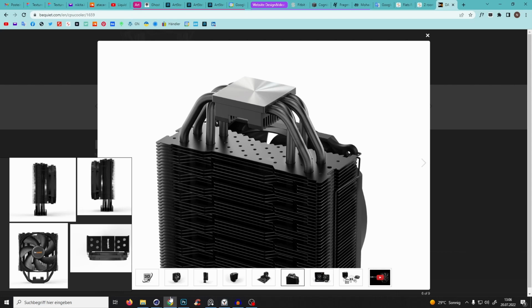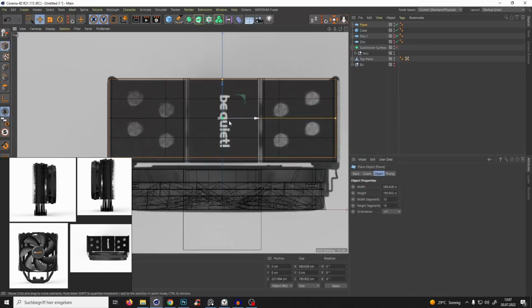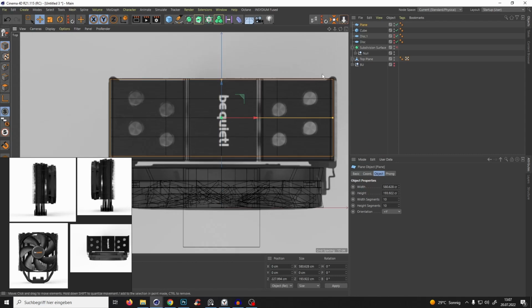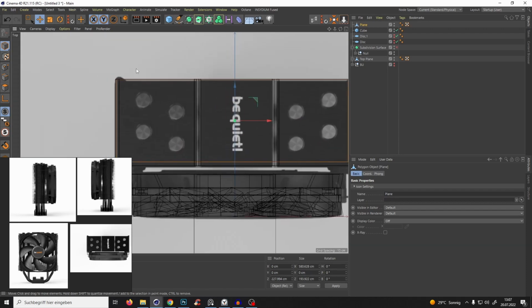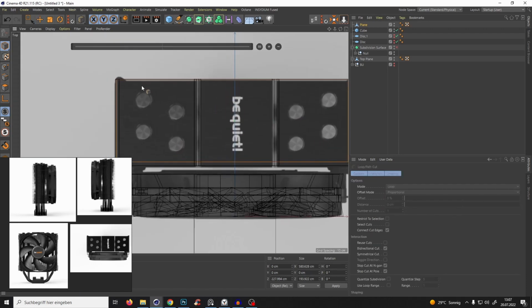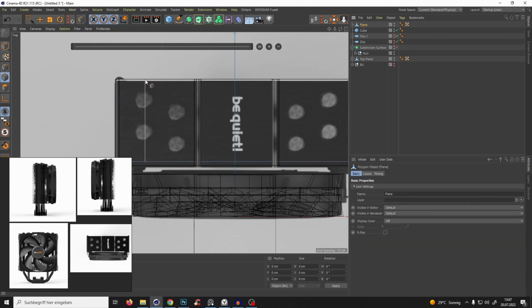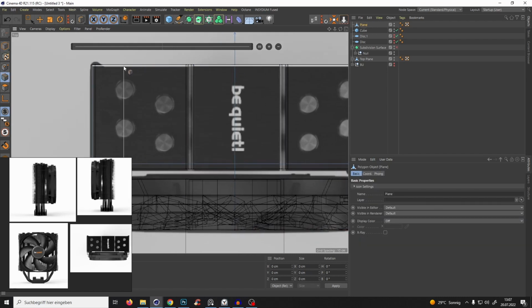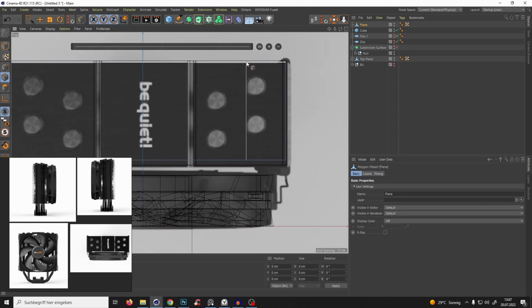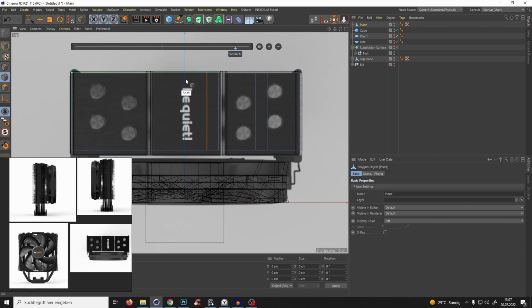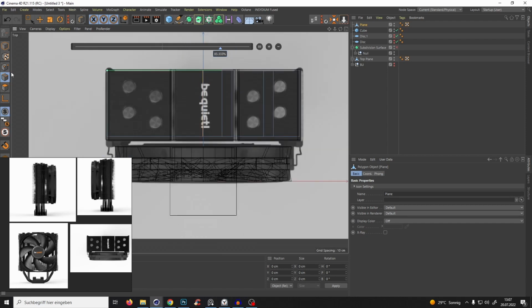okay, we don't need all the details that you can do, but we have our plane here. We give it again just one and one segment, and press C, and let's just add here a line cut with edge mode. Just add here and here. So I have here an edge, then it will go down, then it will go again straight, and then I want it again up. So again I add 2 lines here and one in the middle, because we can again just use a symmetry.